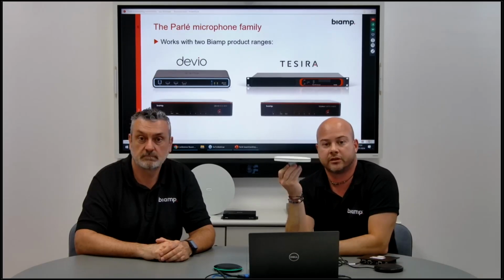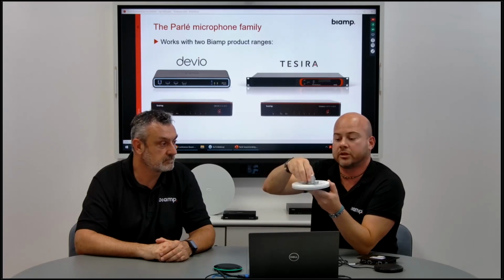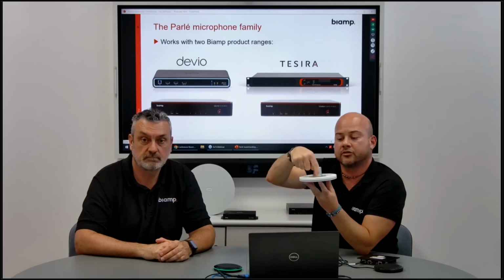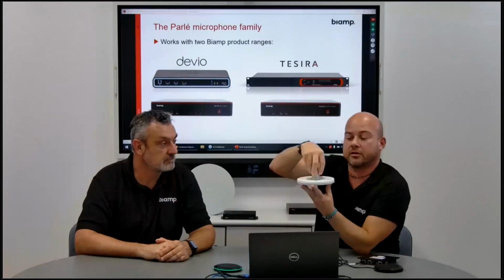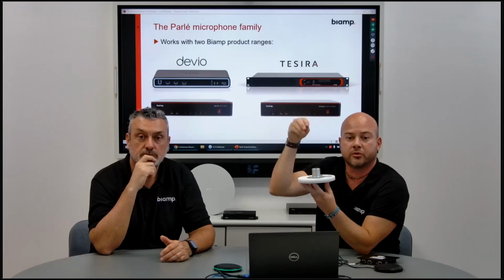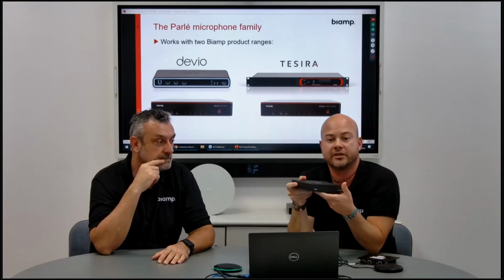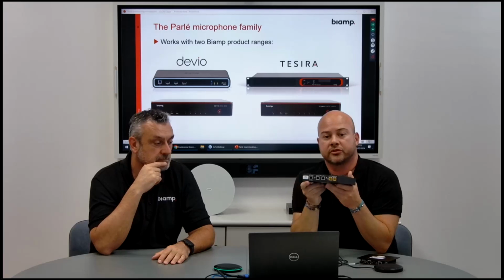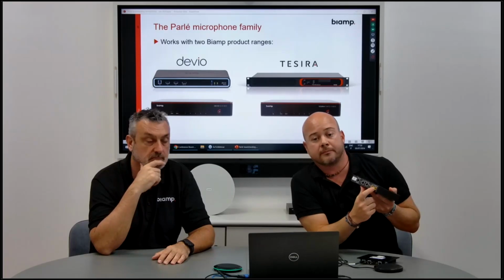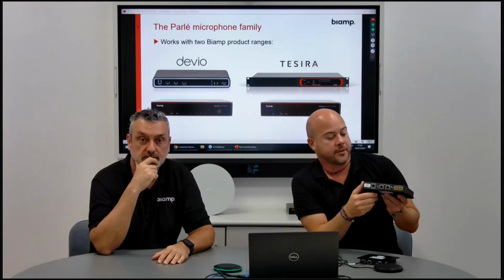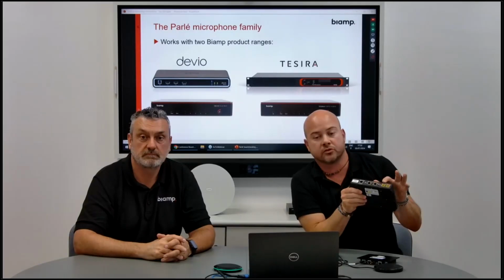Same concept for the ceiling mic. I have the white version here, again, a very sleek design. We've seen the different mounting options with flush mounts, but you can also just put it through the ceiling and screw it with this system. And a very beautiful solution, with an RJ connector on the part here that allows for a very simple connection to the rest of the system. This comes with a mic box. This is the TCM-XA, the version that supports 2 microphones here, and also 2 PoE ports for speakers for 2 channels. There's also the version without the PoE amp outputs, just the two mics.